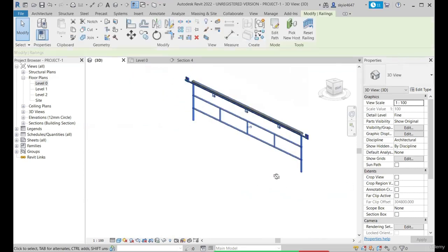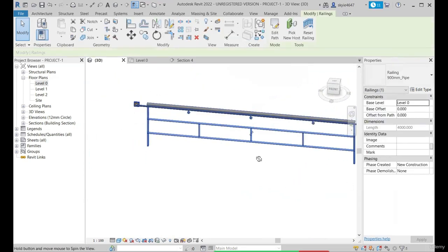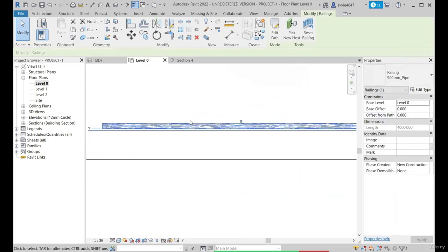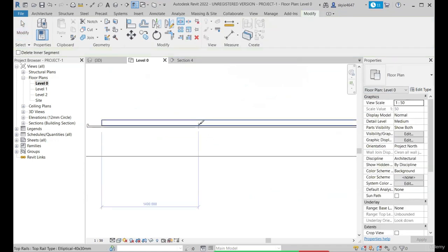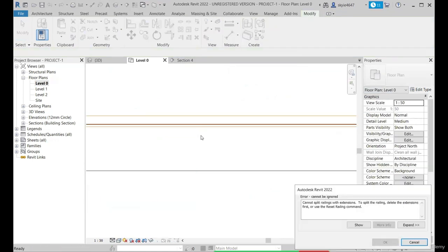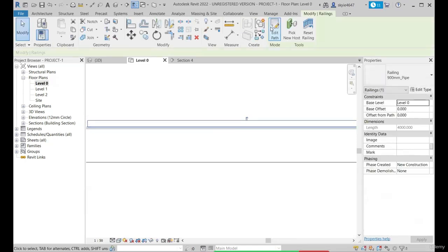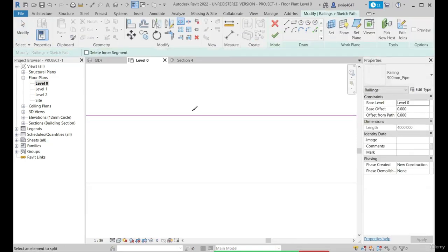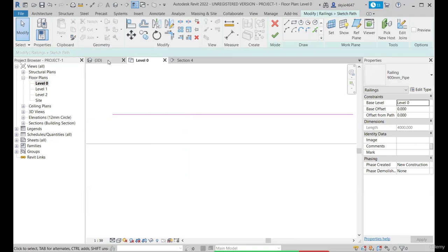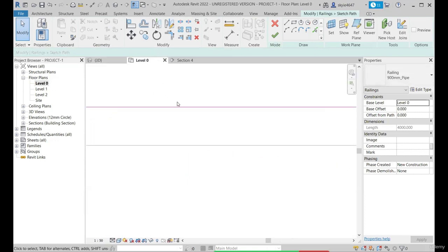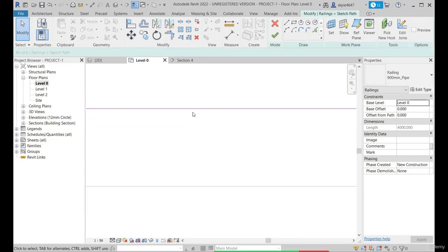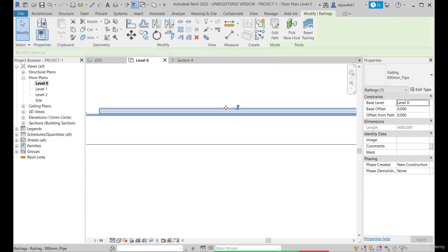And if you want any other baluster or post in between, for example, if you need a post or baluster in between, you can use the split element. You can just edit path and split it in between. For now we were having three balusters in between and two posts. Whenever you split the path in two parts, you can have an additional post created.